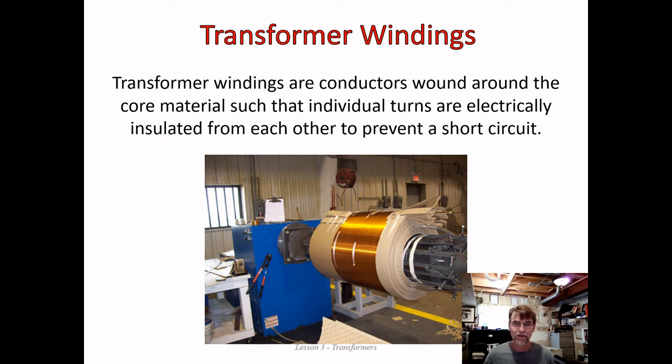The current would come in and short circuit across all of those wires that are touching and exit the other end of the coil of wire. So it's absolutely necessary that there is insulation there, no short circuits, so the current must travel through the entire coil, because it's that coil that gives us our inductance. So even though it doesn't look like it's insulated very often, it absolutely must be.